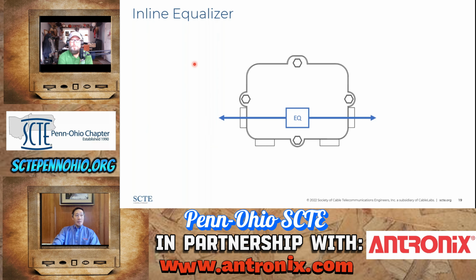One of the passives is an inline equalizer. So what inline equalizers do is they compensate for hardline cable slope. Inline equalizers also pass AC. So there's an RF filter here that is a cable equalizer, and I'll go into that a little bit. And AC routes around that as well. The AC doesn't go through the RF components, but it routes over and through that. There's no fuses associated with it because this is just a 2-port device. Power goes in, power goes out.